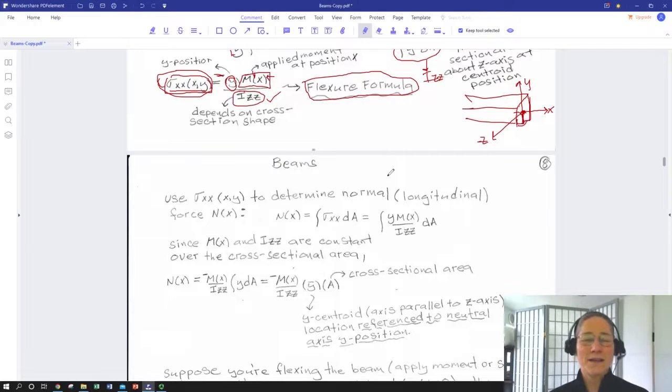We'll look in a follow-on lecture at the effect of a true axial stretch or compression on this sigma xx. It'll add to it or subtract from it, and it'll also actually move the position of the neutral axis. But a general rule of thumb is down at this farthest distance from the neutral axis for most bending scenarios, the tensile stress due to flexure tends to be much bigger than the types of stresses that are practical to apply with an axial load.